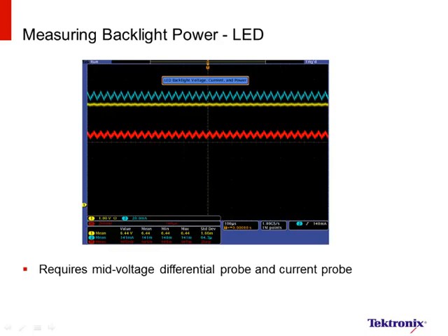The point is that even something as apparently simple as DC LED lamp power measurement requires careful consideration of measurement bandwidth and probing techniques. A power analyzer that is DC coupled and has a high measurement bandwidth, in excess of 100 kHz, can also be used to make accurate high ripple power measurements.